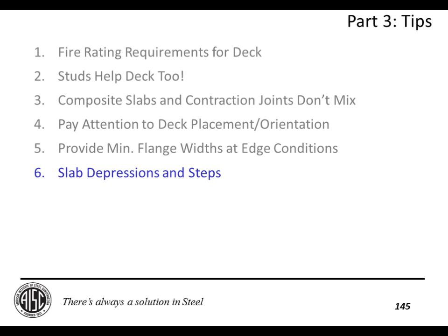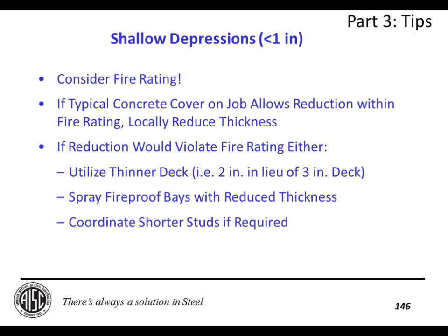Number 6, slab depressions and steps. So for shallow depressions less than 1 inch, be sure to consider your fire rating. Make sure you aren't violating it. If your concrete cover is enough to allow you to reduce the slab depth without violating your fire rating, then just locally reduce the thickness. Shouldn't be much of an issue.